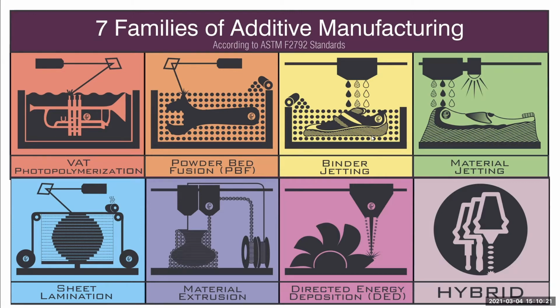Now, obviously, it's gotten a lot more complex than that, and what you see here is just a representative sample. You can have various different types of binder, and you can have colorants and things like that added as well. So you can print in color with binder jetting because the substrate is often just a colorless powder or a plain white powder. You can inject dyes as well as glues or binders to create some really interesting colored objects, or, if you have different chemical reactions that you can inspire, the binder can act as a catalyst on the substrate to create various different things in that process.